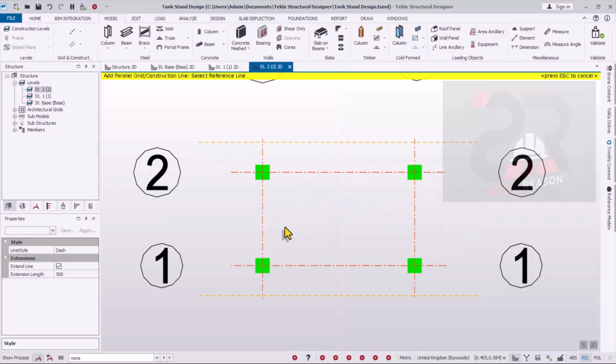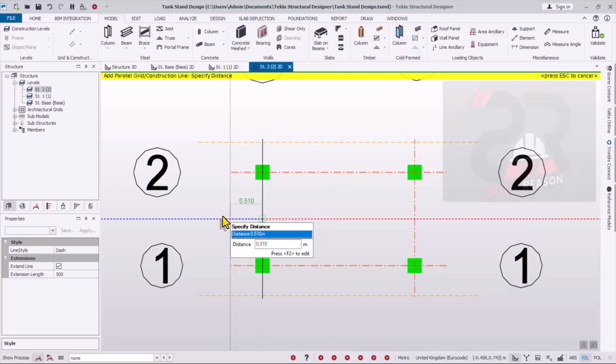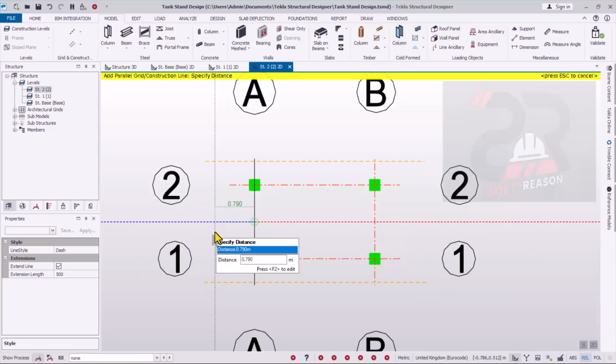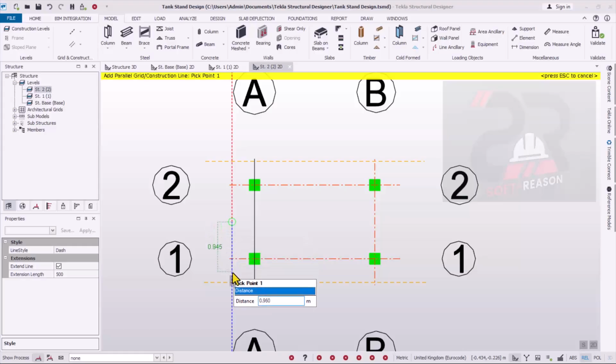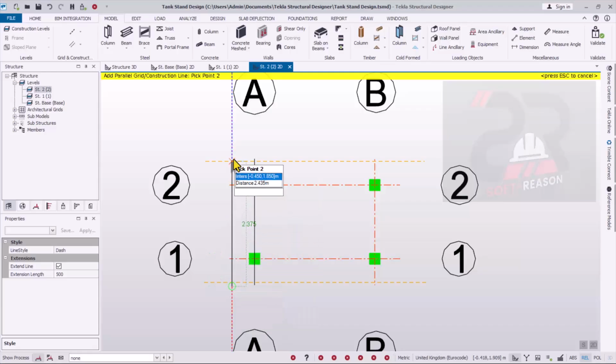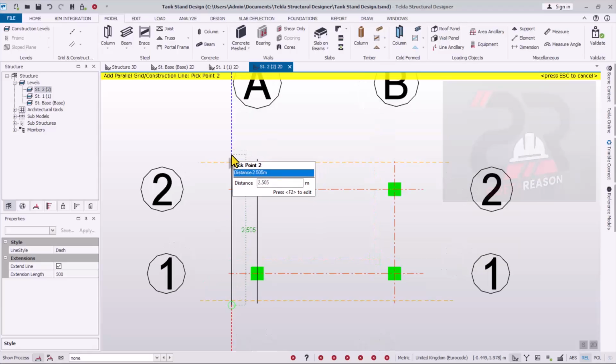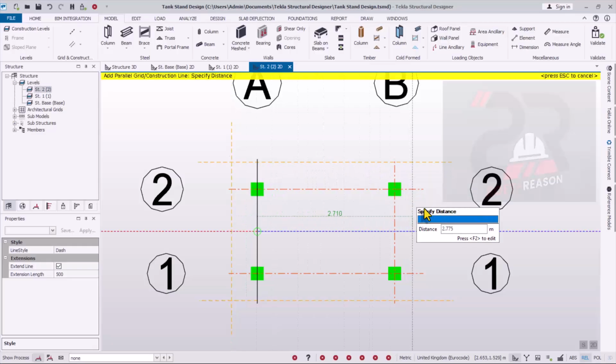You escape. We want to start from the direction of grid line A and B. So A first, you can see F2 on the keyboard, 0.45. Enter. All right, so now you move your hand to where you wish to start this grid line. I want to start it elsewhere. Pick that point where you want to end it. Elsewhere right here, just picked here successfully.